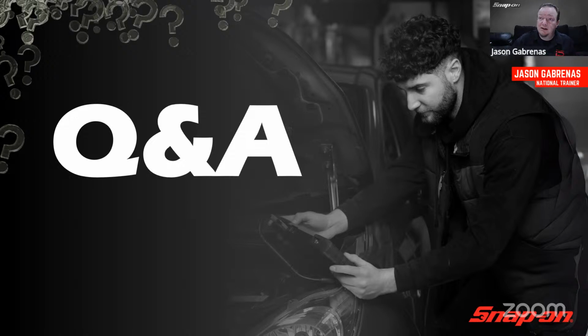Hey, as you can see, there are quite a few different things that can be done with the guided component test and the scope. So he said he fried an injector with a power probe. He loves that tool, but it doesn't care if you push the wrong button. Yeah, that's for sure.